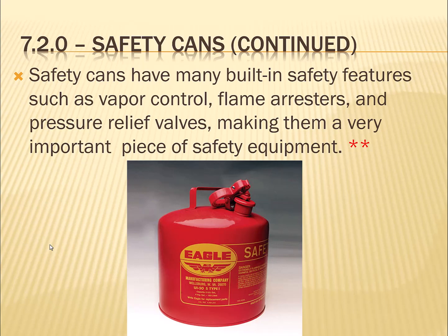But here's the reason it's made of metal. It has to be made of metal. It's because as you pour gasoline or some other fuel from one container to another, the two containers are supposed to be bonded to each other with an electrical wire. You can't do that with a plastic container, so you cannot control the static charges. That's why these containers have to be made of metal.